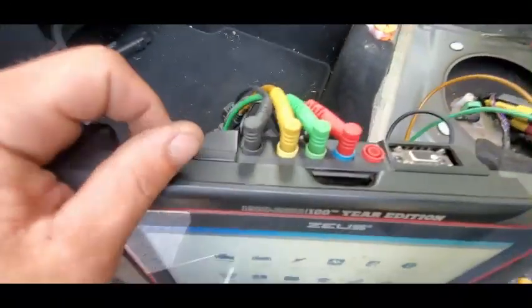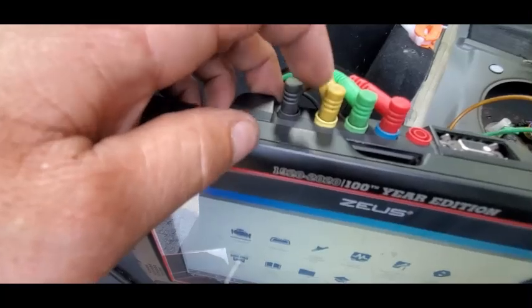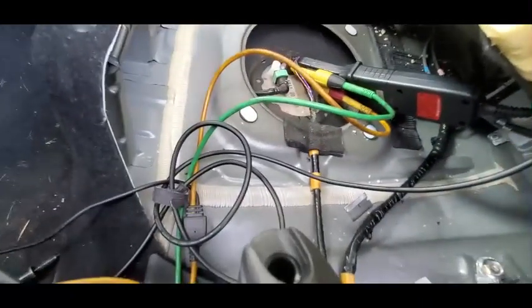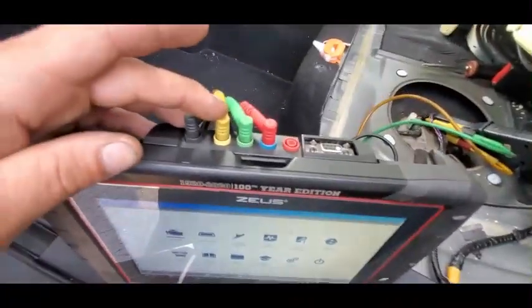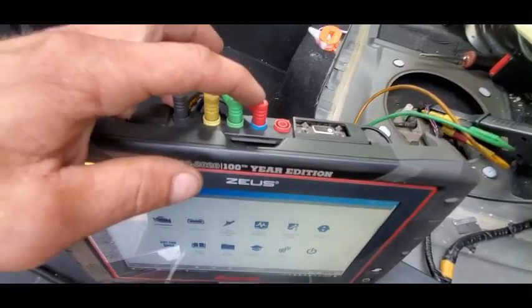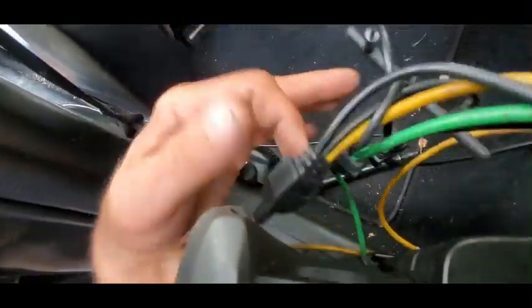Up here, yellow's in yellow, green's in green. So trace 1, 2, okay? So pump, what did I say that was? Yeah, this is gonna be pump. The yellow is going to be pump positive and the green is going to be pump negative, and then this is our amp clamp and our blue trace, okay? And then we have one ground coming from our yellow, and then everything's stacked.